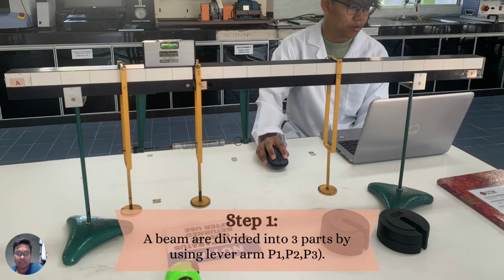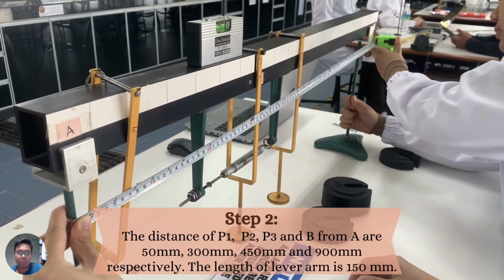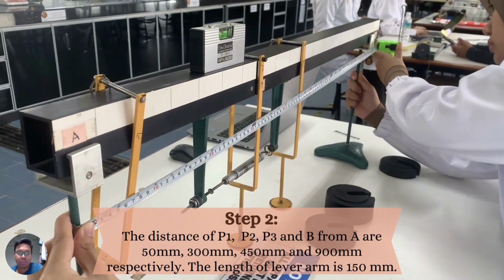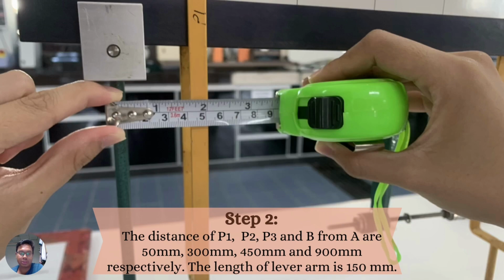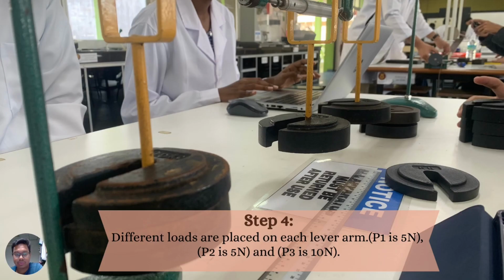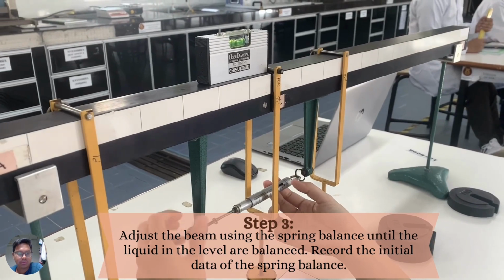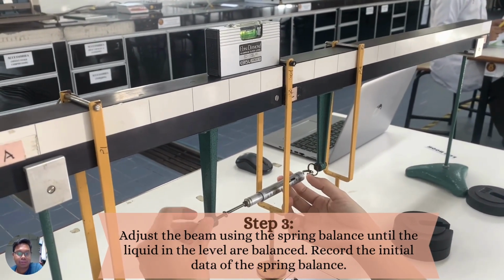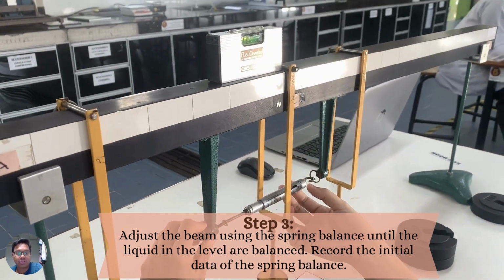A beam is divided into three parts by using lever arms, P1, P2 and P3. The distances of P1, P2, P3 and B from A are 50 millimeter, 300 millimeter, 450 millimeter and 900 millimeter respectively. The length of the lever arm is 150 millimeter. So step 3, adjust the beam using the spring balance until the liquid in the lever arms is balanced, and then record the initial data of the spring balance.